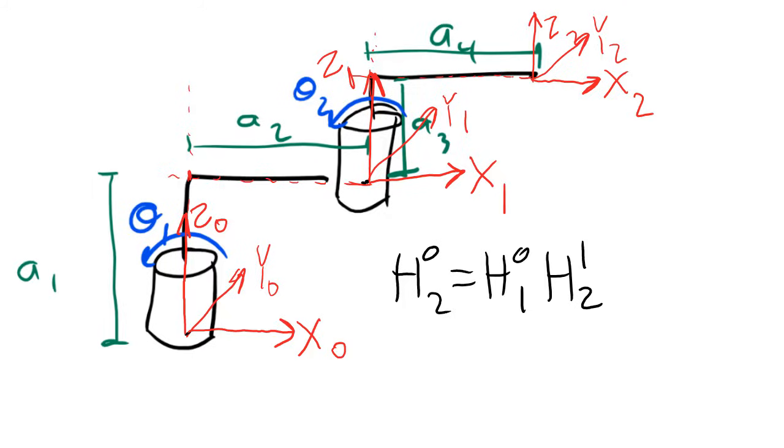Inverse kinematics, as it turns out, is a somewhat more difficult problem than forward kinematics. Let me start by giving you a brief example of why inverse kinematics is difficult. Here I'm showing the kinematic diagram for the manipulator we've built. We know that we can find the complete homogeneous transformation matrix from the base frame to the end effector frame by multiplying together the two individual homogeneous transformation matrices. In previous videos, we've already found H01 and H12. Let me remind you what those are.